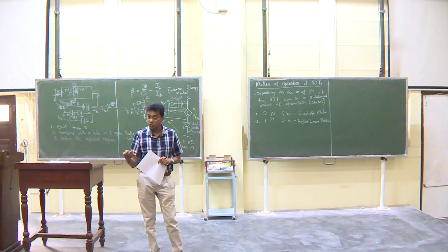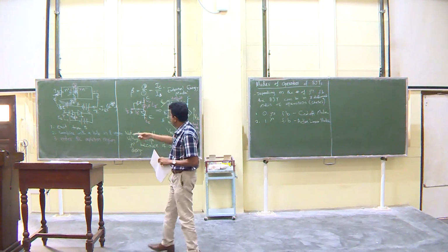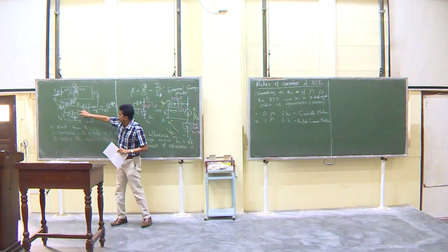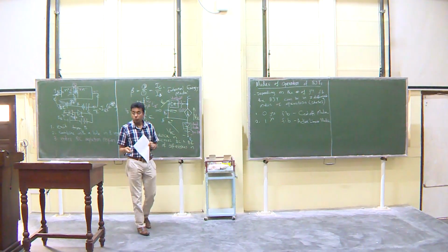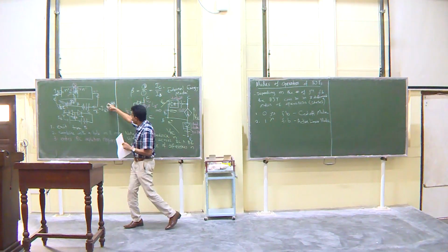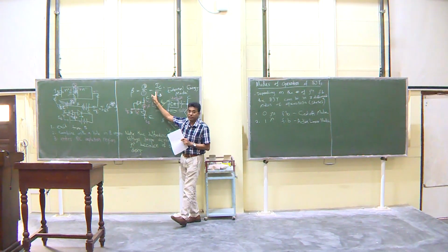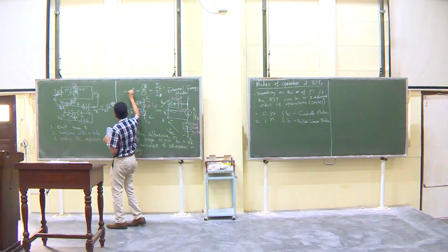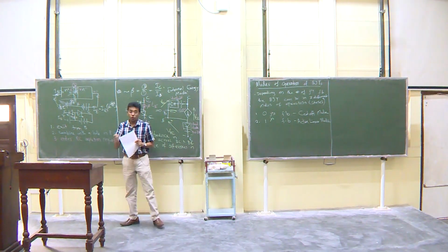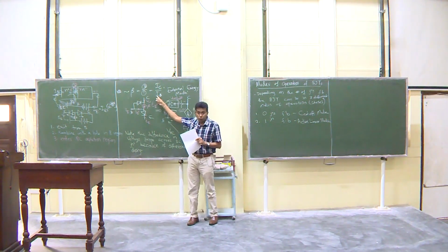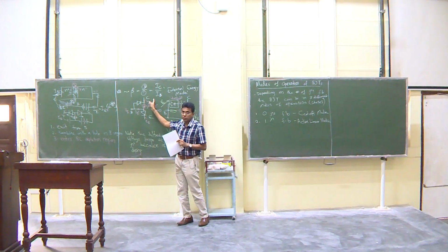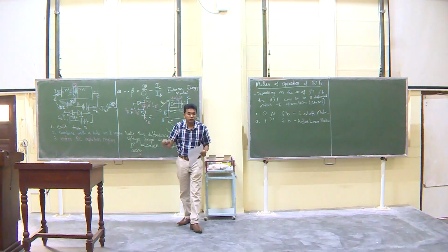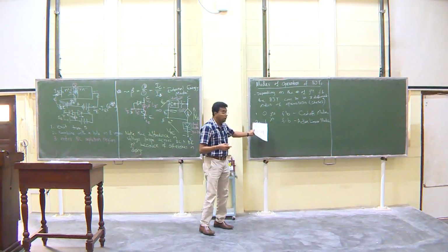We want the transistors to operate in this particular manner, with this one reverse biased and this one forward biased. That is what we want in order to get amplification, because under such situations we have this behavior. Typically, this beta value is large, in the range of 100. So, by controlling this IB, a small value, I can control a much larger current. I can generate a much larger current using this small current. That is where the amplification comes from.